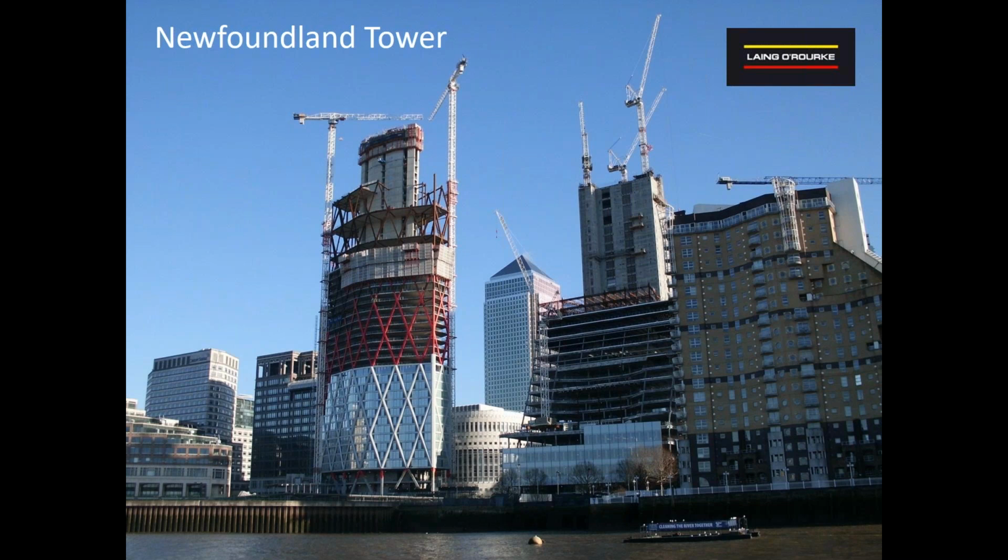Use of bridging columns on that project. Back in Newfoundland, what these slides are moving on towards are looking at ties and the various options for how ties can be achieved. So I mentioned 20 or 30 meters in terms of vertical intervals. And at Newfoundland, there were thrust blocks attached to slabs to which the ties were attached.